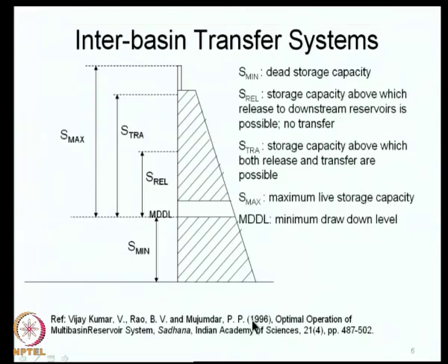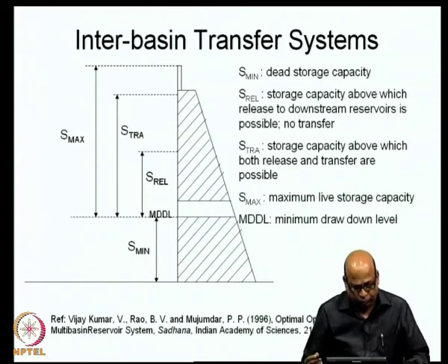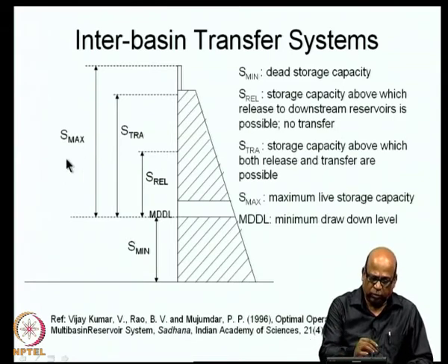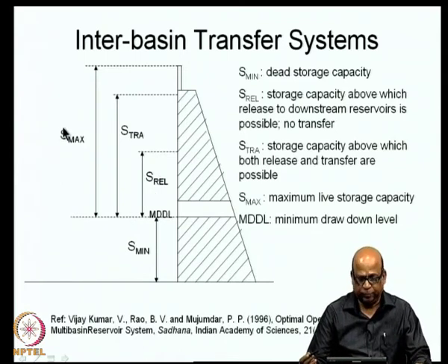So, these are the two questions that we will answer. In answering those, as I said, you need to look at the zones, storage zones, and then ask the question, what should be my optimal SREL, which is the storage zone above which release to downstream reservoir is made, and STRA, storage zone above which you make the release for the transfers to other basins. That is the idea, and this we need to do for each of the reservoirs. So, these values will be different for each of the reservoirs obviously.